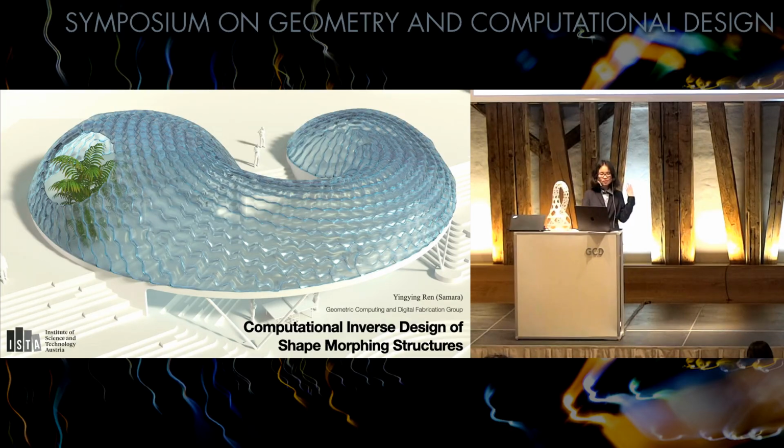I can talk a little more about our construction. The material we use is woven nylon coated with TPU, a plastic layer. The process, like the image I showed, is that the laser melts the plastic parts and causes the fusing. To prevent them from separating easily, we also have a special dye that we deposit along the fusing curve to help with the laser absorption.